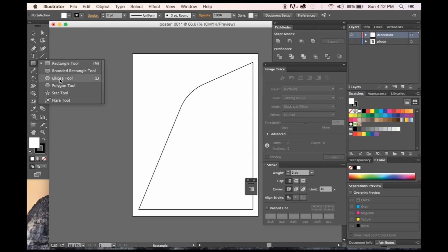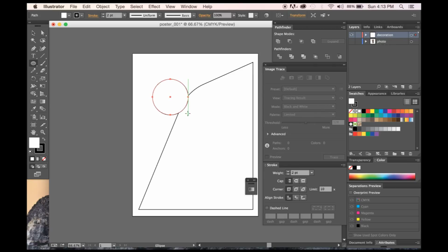I'm going to go with this ellipse tool. And let's say that I want this to be the same height as width. Holding down my shift key, it scales that to be proportional. Now if you notice that this is blocking out the line, that's because my fill is white. If I want to see the line, then I can click None. And there I can see the two objects.